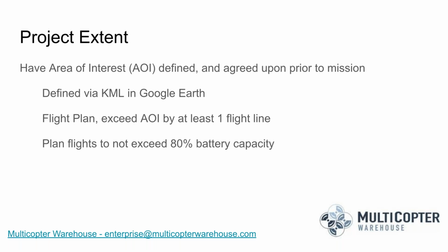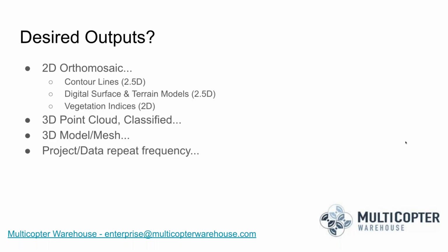Right. That's not to say that a mission should be less than one battery worth of flight. Make sure you're on the ground at 20%, swap the battery out, and then you can hit resume and go back to the mission, and it will continue flying automatically. So that's what we're saying, is don't push the batteries just because you're doing a mapping mission. It's not good for them.